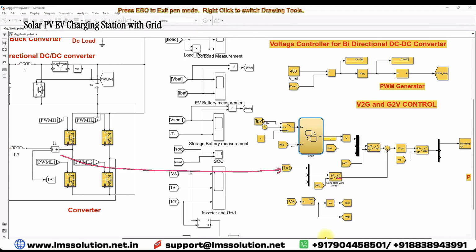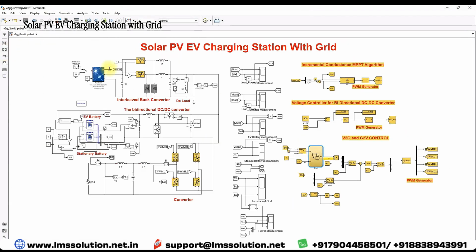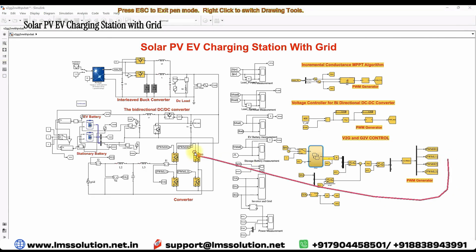After the conversion, the actual and reference dq naught are going to be compared here and processed via a PI controller, and then we are having the controlled voltage in the form of dq naught. Again you have to convert to alpha beta naught, and then you have to take the first quantity, nothing but alpha, and it is going to be processed via sinusoidal PWM. It will generate the pulse. So this pulse is going to be used to control this inverter, in the current control concept.